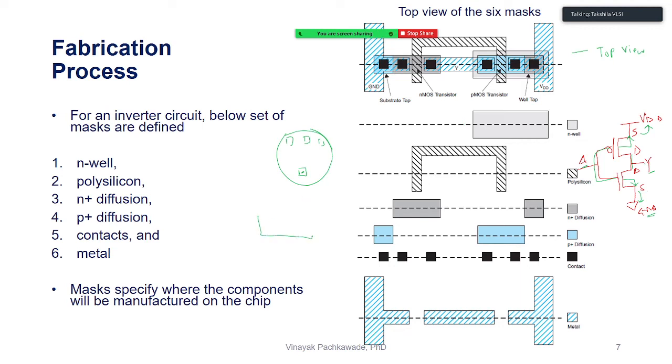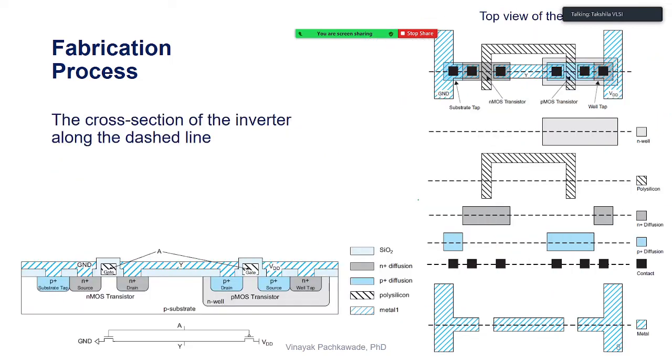For example, this is the cross section. You need to understand this very well actually, okay? Don't miss this. So this is your p-type substrate, and here somewhere we have the N-well, and then here you have these two transistors. This is N plus. So we have seen that. Okay, I show you here. Look here. So I have this p-type substrate. I have NMOS here, I have PMOS here, and I have well-made connections with the mask. So this is called the side view or cross section.